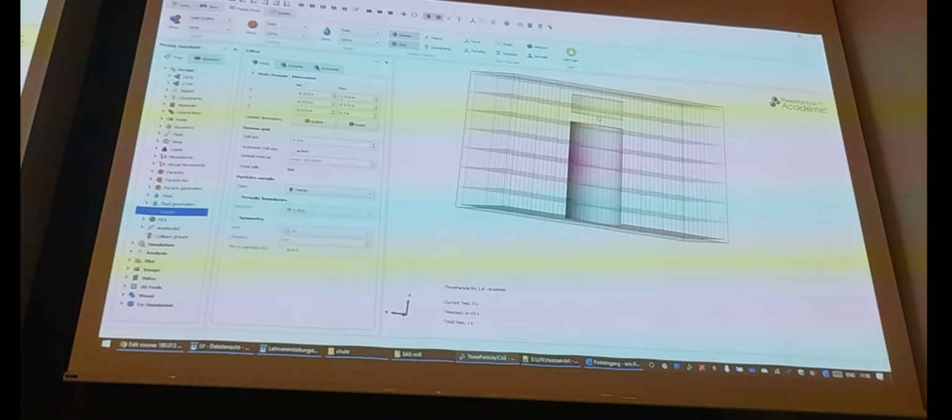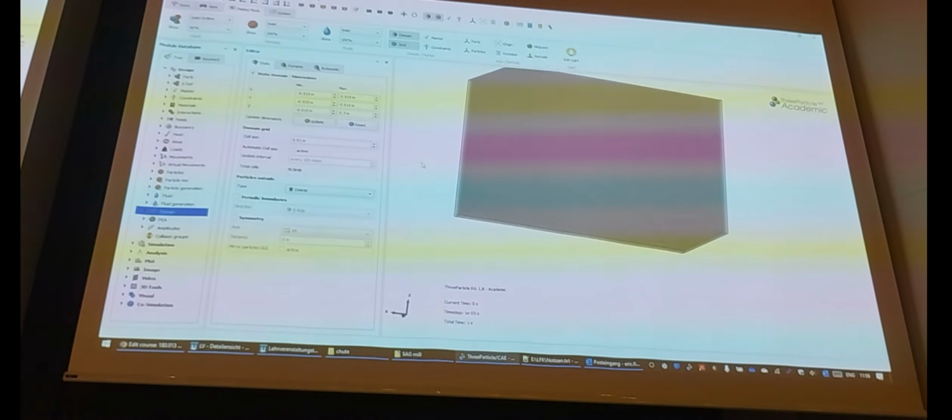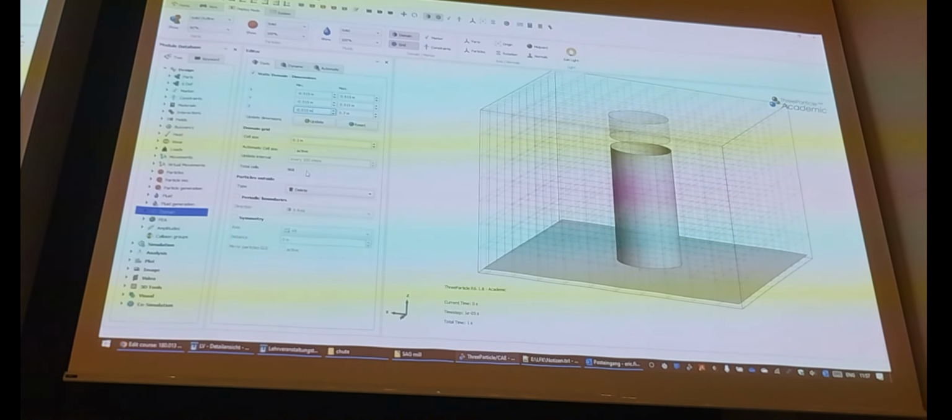So if you have a very small cell size, for example, like that, much more cells. More to compute. If it's bigger, something like that, it's okay. Not that much cells, about 1,000. That's okay. But the computation of the contacts might be a little bit more complex. So there is a trade-off in either direction.